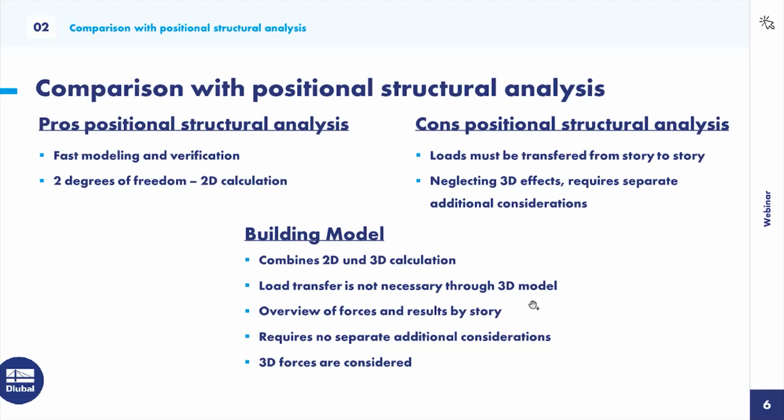Also, which is a good point, we have an overview of forces and results by story. That's also a new point, which is only possible with the building model add-on. So this analyze by story. So you have directly an overview over all results, from deformations to forces.